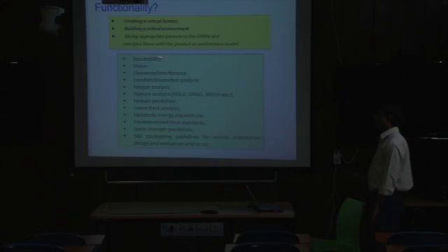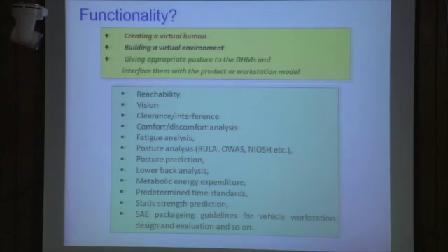Those include reach analysis, vision analysis, clearance interference study, comfort discomfort analysis, fatigue analysis, various types of postural analysis using various postural tools like RULA, REBA, OWAS, NIOSH, etc. Then posture prediction based on preset criteria, lower back analysis, spinal compression forces, shearing forces we can analyze.